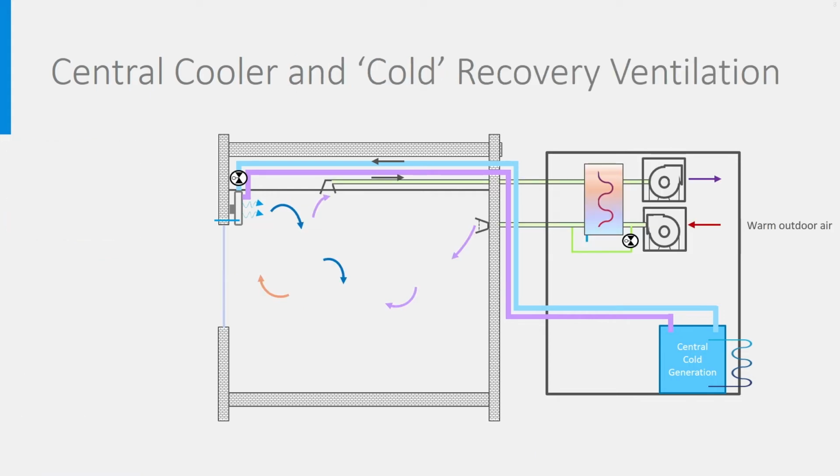And of course, here too, it is possible to apply mechanical supply and exhaust ventilation and to recover some cold from the indoor air when it is very warm outdoors. Here too, you see a bypass to the recovery heat exchanger and a drain, as cooling may mean condensation.